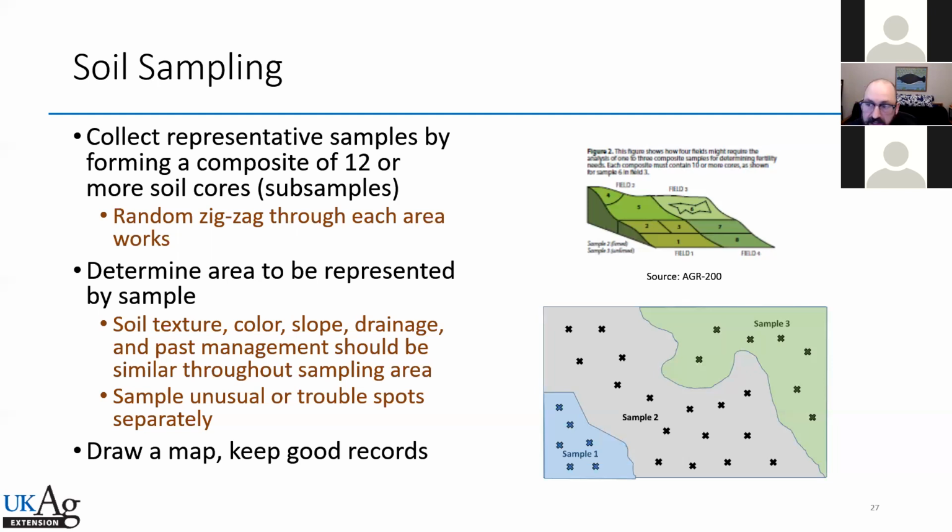As far as natural features, topography, slope, and elevation tend to track with nutrient need. So side slopes, tops, knolls, and bottoms tend to be very different. So if you wanted to do a little eyeball precision ag without getting too fancy, you can have a topographic map that you download off the internet or web soil survey. Go onto the web soil survey of NRCS. If you Google that, you can actually find your farm, draw a box around your field, and it'll tell you everything about all the soils on that field and slopes and all of that stuff. And you can sample them differently.